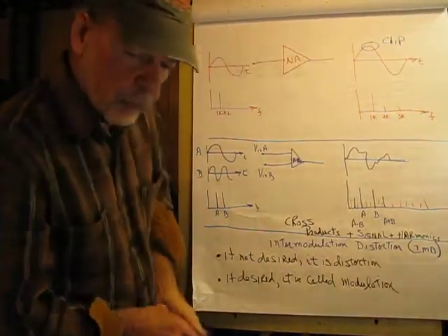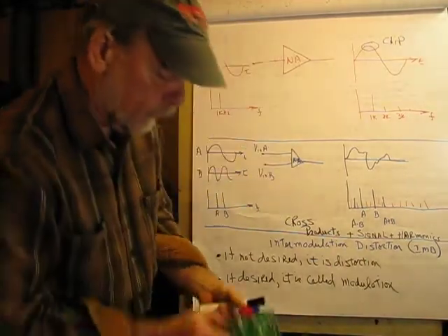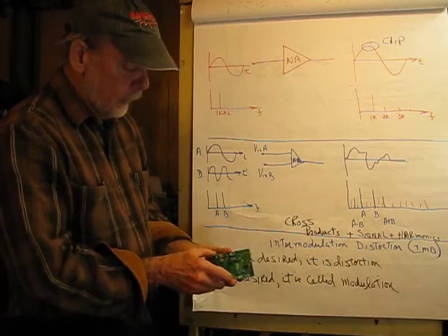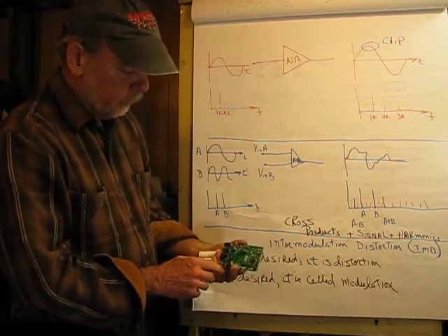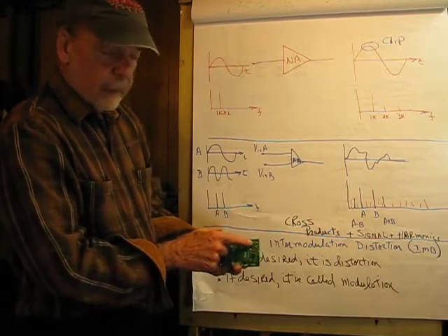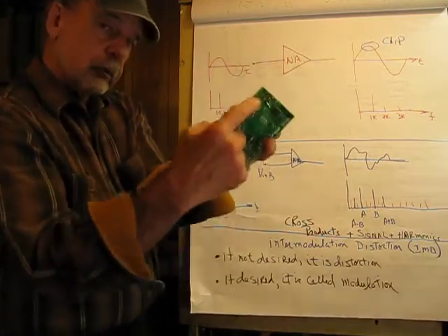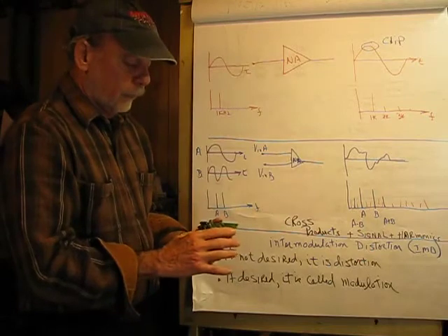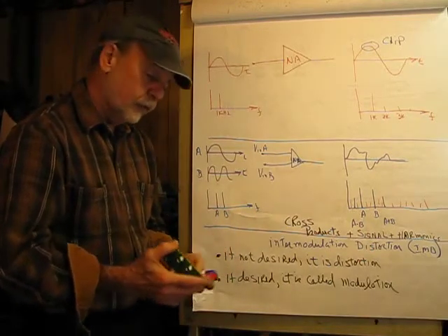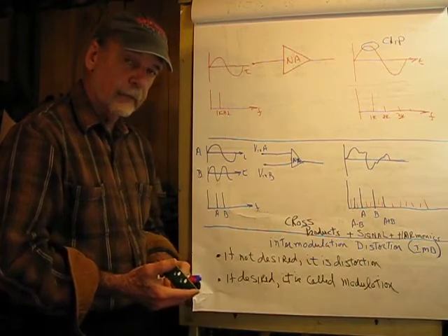And suppose that we have a little device like this guy, and this is designed to run from a lithium-ion battery, and these little guys here are operational amplifiers. A fully charged Li-ion battery is 4.2 volts, and its cutoff voltage is 2.8 volts.